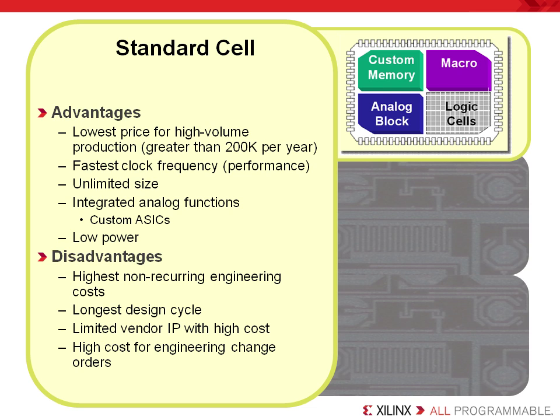The ASIC verification time is longer since a more thorough verification of the ASIC's performance is needed to ensure functionality. Bottom line, testing is critical for ASICs since the cost associated with a respin is prohibitive. Likewise, the tools required for design and test are more expensive than FPGA tools.